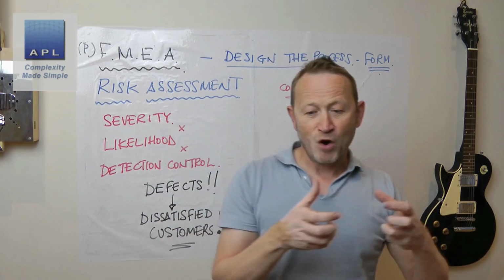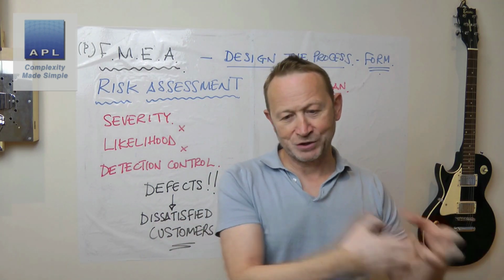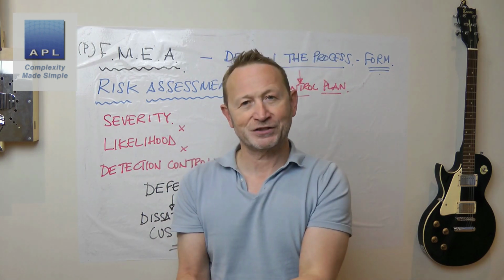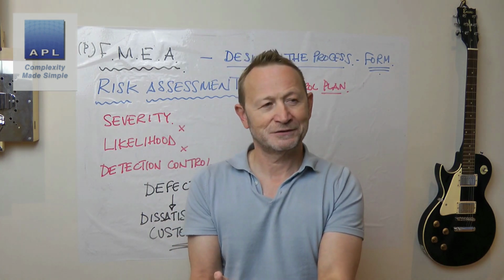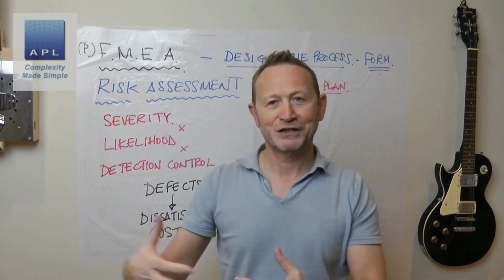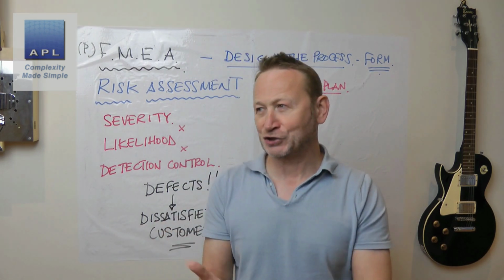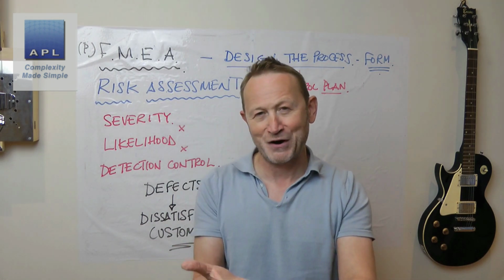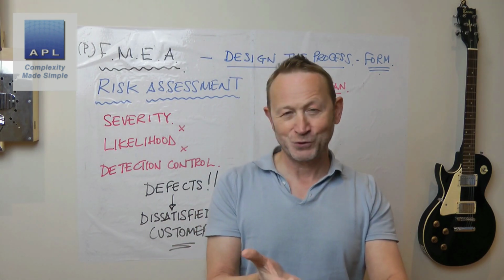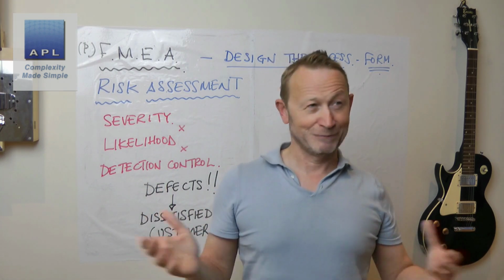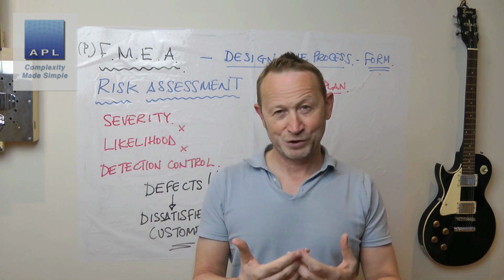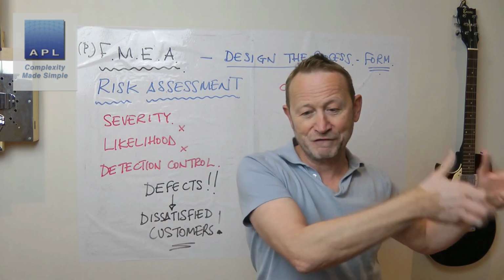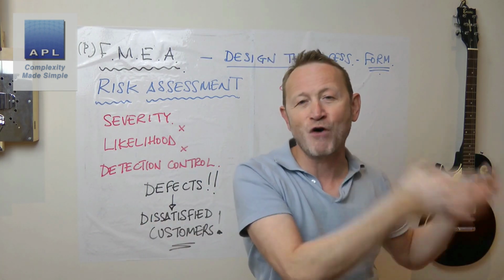Now, if I put that in the wrong box, if I say the failure mode is that I'm going to get white marks in the molding, then I say, what's the failure effect? Now you're having to think forward. You're having to say, well, there's going to be a high scrap rate. Maybe we're going to be late with the customer because we haven't got enough parts. Maybe we're going to delay an order to a big customer. Maybe we're going to lose a big order. Now you have to guess, because you put the failure effect in the wrong box.